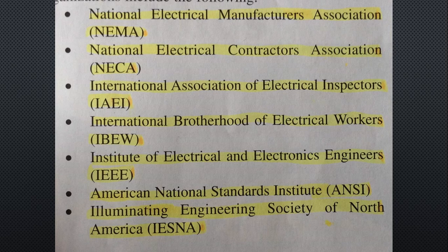A product is listed only for its intended purpose and should be used only for its intended application. Also, just because one component of a piece of equipment is listed does not mean the entire item meets standards. Be sure each component and the entire unit meet the minimum standard for safety. For example, a listed appliance cord does not mean the appliance itself is listed. Check the equipment to see if it has been listed as well.